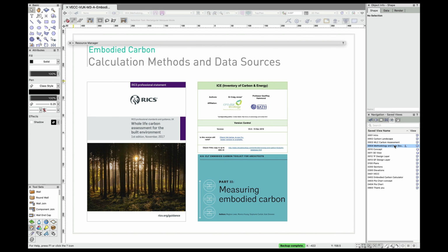That is an open source database which is looking at a statistical analysis of the market to derive an average embodied carbon factor for some of the most commonly used materials in construction. Around 200 default Vectorworks materials have embodied carbon factors from this database, and we keep adding to it. Those values are for a generic material, like a brick, or softwood timber, aluminium, and so on.